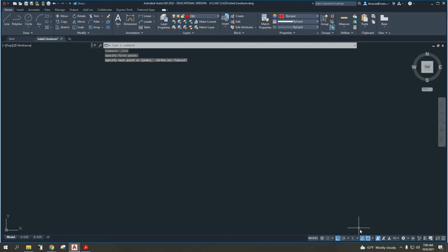Another item that is quite useful is this option, this object snap. Okay, you see that's F11, and O snap, which is F3. And these are F keys on your keyboard. These will help us find things like endpoints of lines, midpoints of lines. And again, we'll make things much more precise because AutoCAD will go to, I don't know, 9 or 10 decimal points to the right of 0.